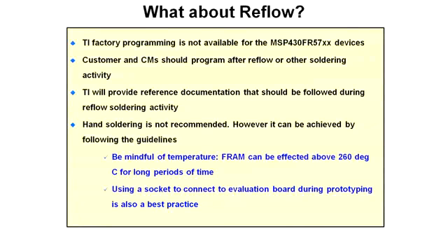Hand soldering is not recommended because you can concentrate so much heat on the part. However, it can be done by following the next couple of guidelines. Be mindful of the temperature. The FRAM can be affected above 260 degrees C for long periods of time. If you use a socket on an evaluation board during prototyping and you're doing a lot of soldering, that's probably a best practice as well.